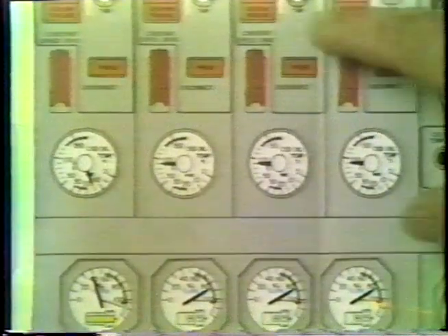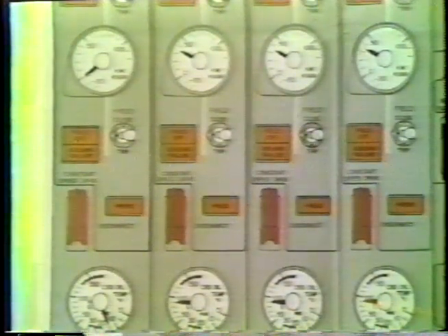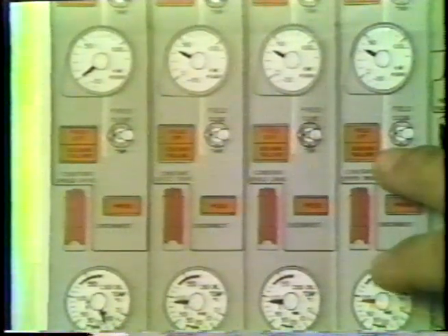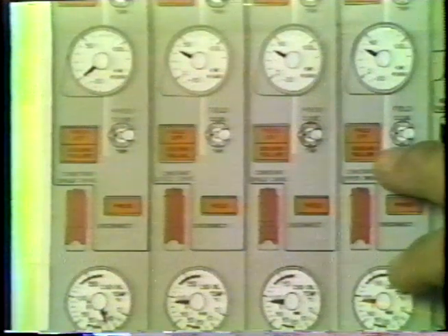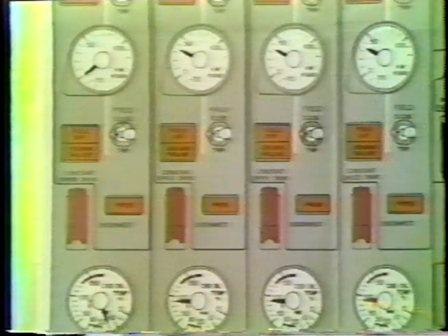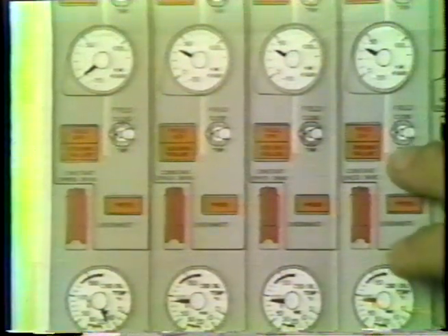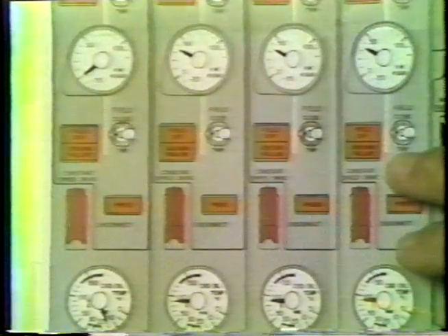Generator bearing failure lights are strictly a generator problem. It indicates that excessive clearance is in the bearings at each end of the generator. They may come on steady, they may glow, or they may blink at you. In any case, it means the bearings are allowing excessive play in the generator as it's rotating. A generator bearing failure light coming on is also a good reason to disconnect the CSD.